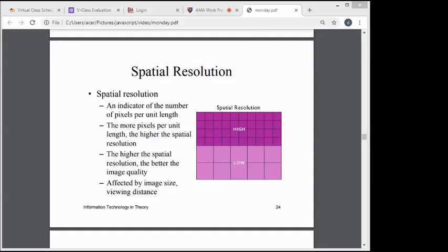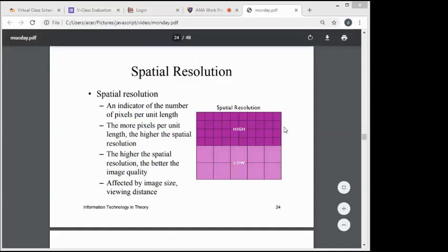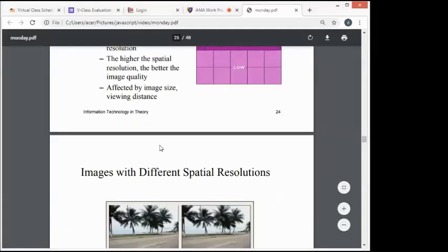Okay, so resolution is the accuracy with which a given map scale can depict the location and shape of map features. The larger the map scale, the higher the possible resolution. As a map scale decreases, resolution diminishes and features' boundaries must be smoothed, simplified, or not shown at all. It is also the size of the smallest feature that can be represented on a surface, for example, a small area may be represented as a point. Okay, so that's our spatial resolution.